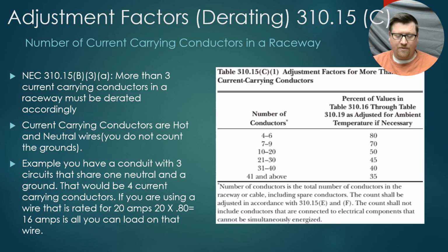All right, so now we've picked out a wire size based on either the 60 or the 75 degree column, depending on the temperature. We have also padded that amperage, right? Before we picked that out, we padded that amperage to say whether this is a continuous load or not. If it is a continuous load, then in that last example, I'm choosing a wire good for 22.5 amps. That's less than 100 amps, so that's going to come out of the 60 degree column. I'm going to be choosing a wire out of that column.